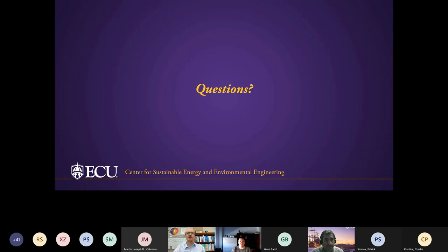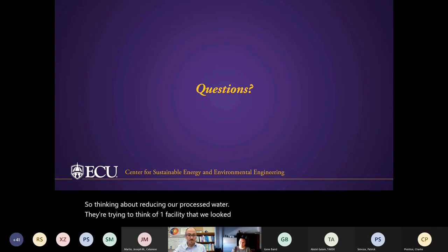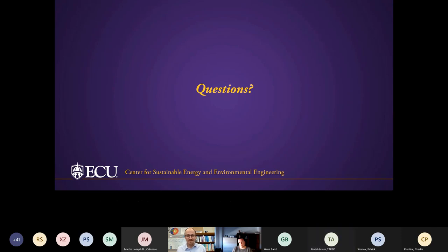Yes, absolutely. So thinking about reducing our processed water needs is an example. And I'm trying to think of one facility that we looked at. One interesting thing is rainwater harvesting. The biggest expense with rainwater harvesting is often just the tank to hold enough rainwater to make it worth your while. And then using rainwater, you usually need to treat it. We think of rain as being pretty clean, but if it's falling on a roof and it's being stored in a tank, you're usually going to need to treat your rainwater as well.